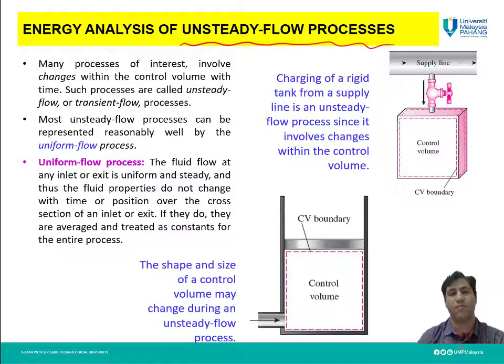we have a fixed boundary for a steady flow process, but here, in most cases, we have a variable boundary for the control volume, and also for the energy balance we have a change in the energy of the control volume.